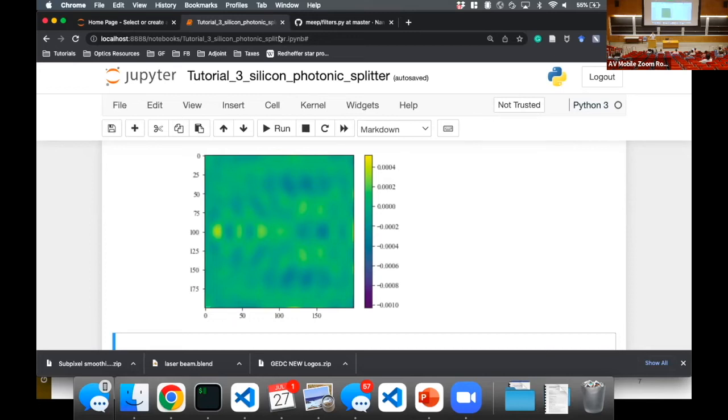Perfect. Thank you. Are there any questions? Yeah, Arjun. What's the advantage of defining your symmetry in the mapping function versus using the built-in symmetry? Yeah, so his question was, what are the advantages of defining the symmetry in the mapping function versus a lot of the symmetry conditions that Meep already supports? There's actually two reasons. Number one is because there's a current bug in the code, which we recently reported. We've been adding a lot of features to the code base, and along the way, we've been breaking some things. So previously, you were able to take arbitrary design regions and overlap them over each other, and it'll automatically average them for you at the end of the day, like what Arjun is suggesting right now.